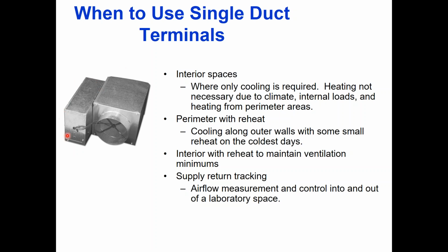Interior zones, this is the kind of box you're going to use for almost every project. It's cooling only. There's no reason to have a heater on an interior zone because, like I said, all of its neighbors, left, right, front, back, up, and down, are all warm 70-degree spaces or whatever.